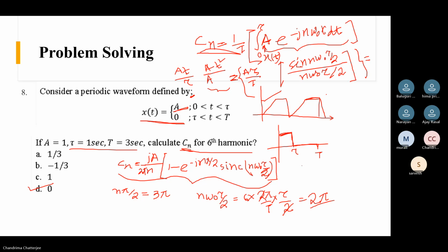Usually we use KiCad or Altium. Yeah, exactly, that is what I wanted to know. In EMI/EMC, there are some guidelines, for example if there is a switching device, you should not keep it near the sensitive analog system and other things. So there also we can learn.